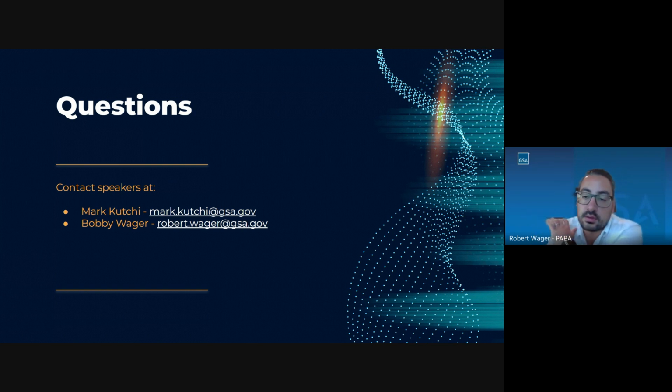That said, okay, Mark. I also will add, take a look at, I don't know the section off the top of my head, but in section 1 General in the P100, the renovation alteration section, it talks about that. In a lot of cases, you need to include in your scope of work the P100 requirement if you want to update this floor drain. Meaning if you want to put in the floor drain, you might make sure your scope includes a floor drain and your budget includes a floor drain. So yep, thank you. Take a look at that.